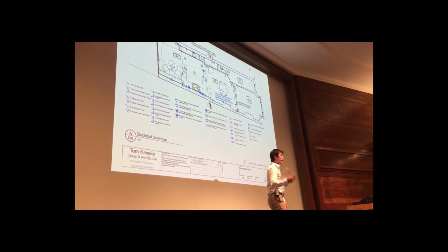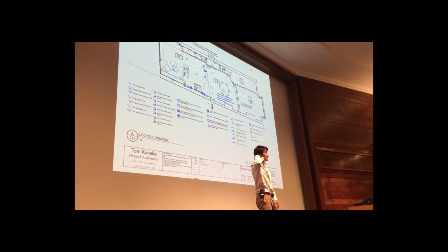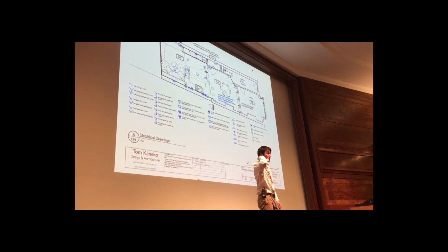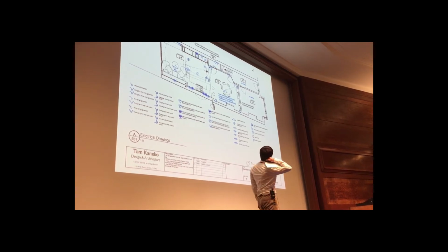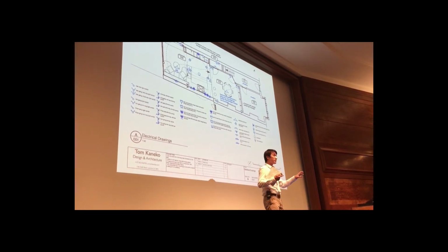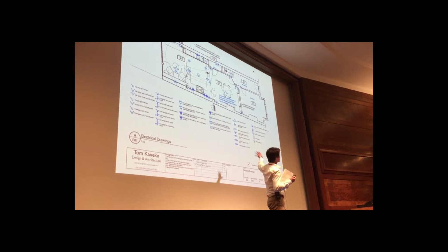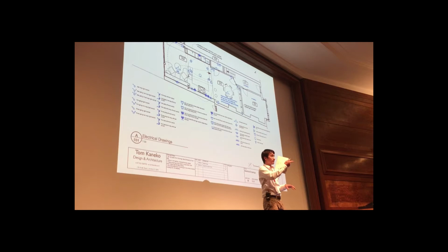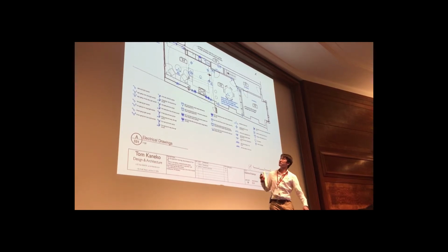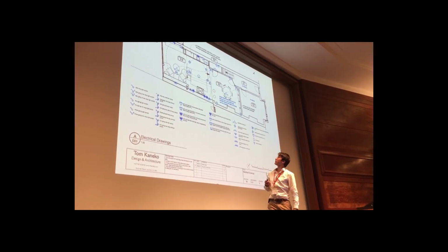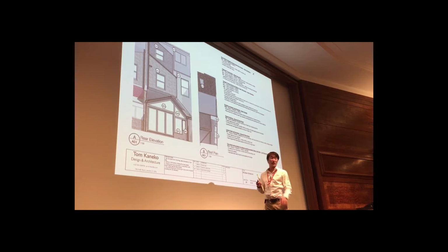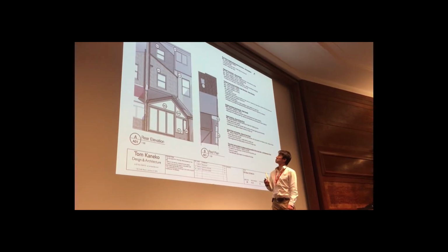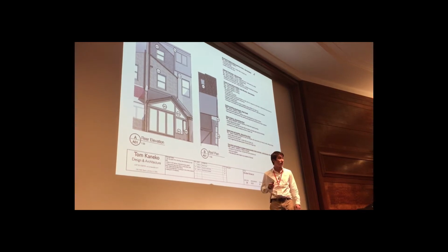And of course, when it comes to electrical plans, you just get the basic plan in just a black and white plan. Then I put all the symbols on. The electrical symbols are actually bits of scrapbook I use in my Layout, and I just lift them in and get your electrical drawings. I've started doing window schedules like this too, which is understood a lot quicker.